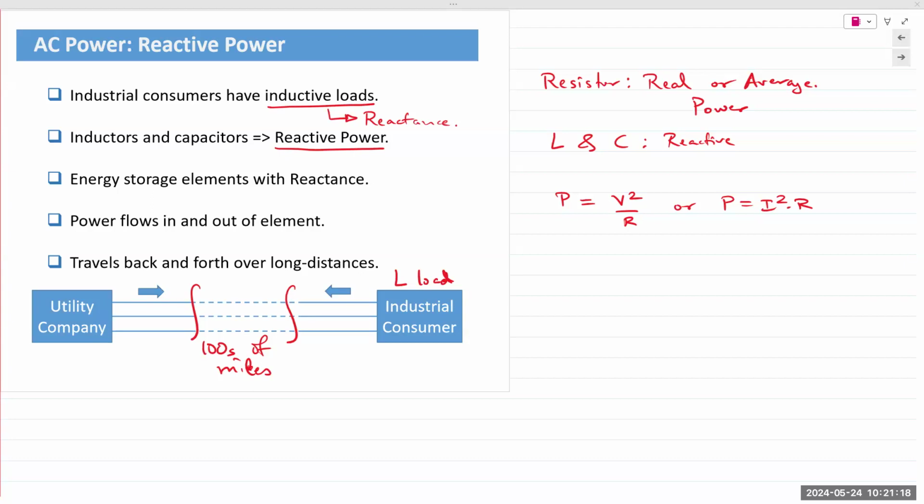And again, that goes back to that first power station that was set up. Remember, I stated in that talk where the first power station was set up with an average value of 100 volts to 110 volts. And once you have infrastructure set up to that voltage, you can't change it without it costing like trillions of dollars. Okay. And so North America uses 100 or 110 volts, whereas the rest of the world, which came later, decided to choose a higher voltage. For the same amount of power, if you increase the voltage, you now only have to transmit lower current, which will save you money because losses are not as high. It's all tied together.